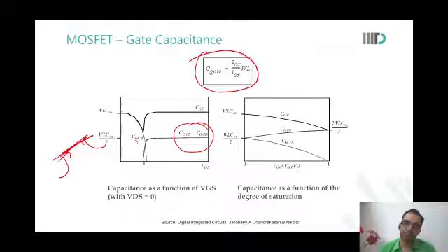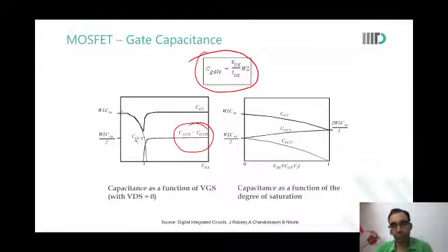Okay, but at lower frequency, when the inversion is forming, is the charge coming from the body itself, and then also from source and drain? We've already shown it like this, that it is coming from source and drain. It is showing that when VT has been reached, then it's coming from source and drain. So this is the VT point. Right.